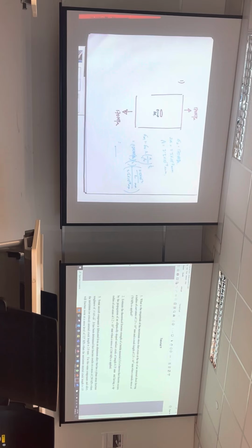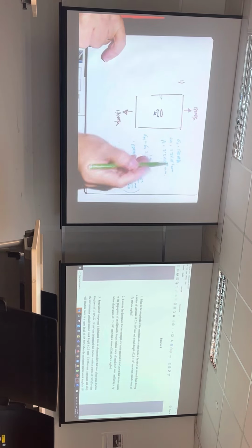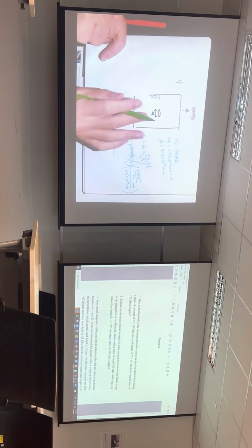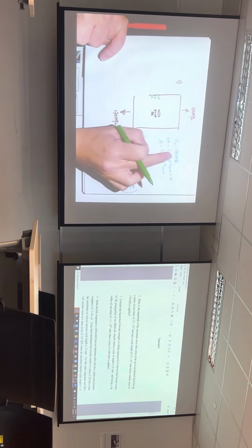If the question has changed a little bit to say that this is a surface crack of this dimension, then this value will be equal to A. Okay? Surface crack, the length is given by A. Internal crack is 2A, so 2A equals this value for an internal crack.